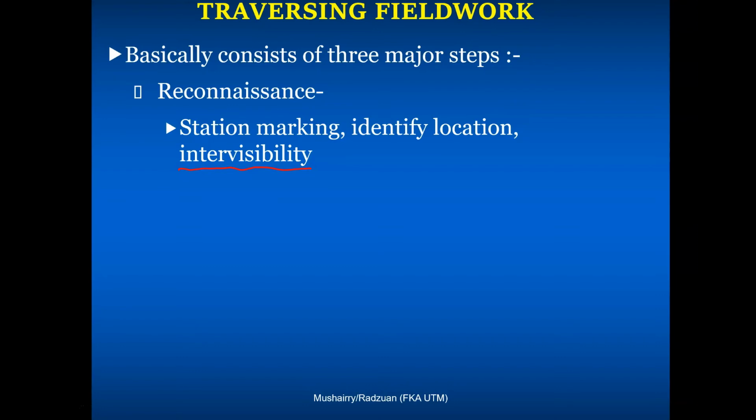You can actually see the adjacent stations, because if you can't see them, you cannot measure the distance, and obviously cannot measure the angle. So you have to spend a fair bit of time doing this. Give a good thought about it, because planning is important.